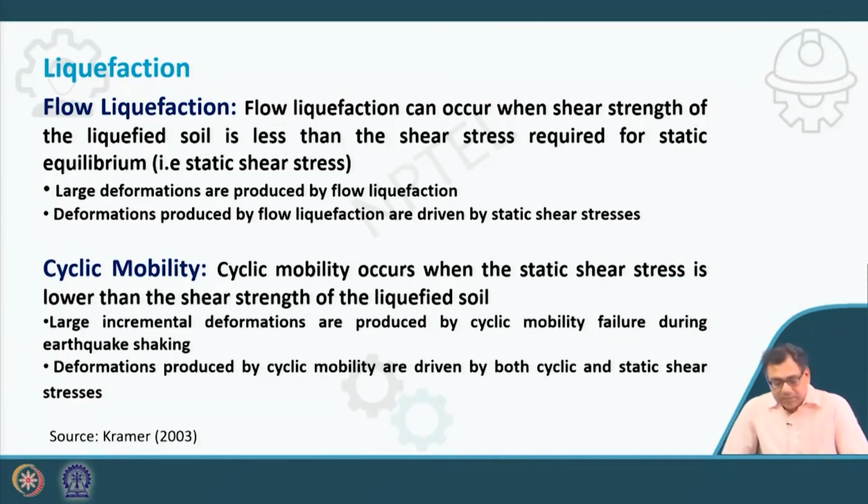But cyclic mobility occurs when the static shear stress is lower than the shear strength of the liquefied soil. That is why the deformation produced by cyclic mobility is driven by both cyclic as well as static shear stress.